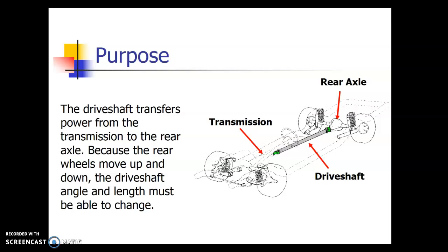Basically, the last thing we talked about was transmissions, specifically automatic transmissions. Up until this point, we've discussed the internal combustion engine, how we make power, and all of those intricacies to make a little shaft turn out of the back of the engine, and that goes into a transmission, which you see in this picture right here. That is there for gear reduction or overdrive, depending on what purposes and load the vehicle is being operated under. Well, now, how do we get the power out of the transmission and down to the drive wheels? That really depends on if it's a rear-wheel drive platform vehicle or a front-wheel drive platform vehicle.